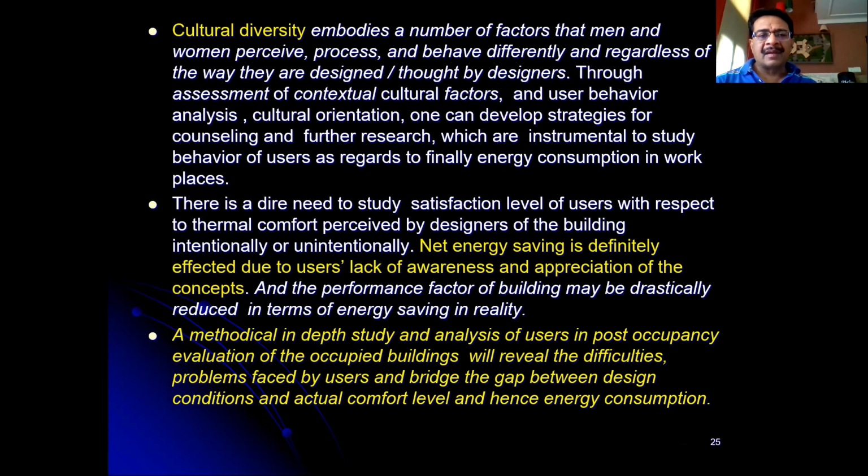I tell you another problem. There's another failure. It's not a failure, it's a limitation. For example, I designed the building to having a floor to floor height of 3.9 meters, thinking that 1 meter space is sufficient for accommodating structural and services. But we just wanted to maintain 2.90 as the height of the floor below the false ceiling so that the space gets adequate daylight and the penetration is deeper. But actually speaking, when the whole process worked out with the services, with the clients and final working of things, we were not able to deliver 2.90.